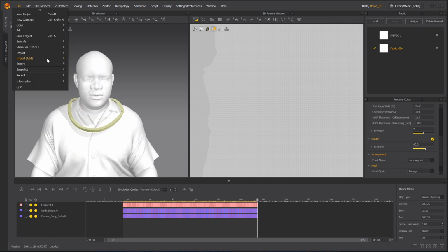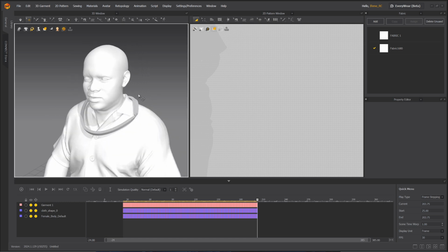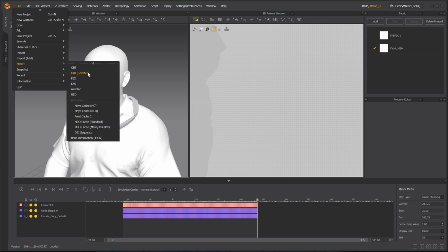I like that this mistake came up, because some people will be like, oh, I already pressed it, why is it not at the same angle that I left it in play? That is because you actually did bake it from the original. Marvelous Designer is garment creation software, so you first create the garment before you bake. You have already pressed the space bar to simulate, as if you are creating the garment before you bake. So this is just a lesson: bake it directly from the position it's at. You can just adjust some parameters and make sure you always bake it from the base position you imported it into Marvelous Designer. So let's just do the whole export again and move into Blender.